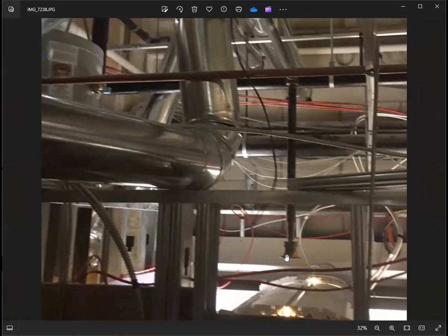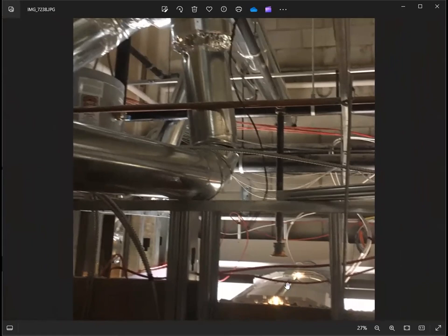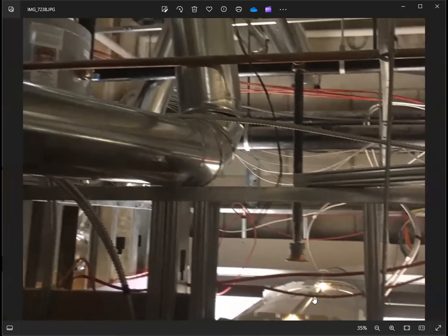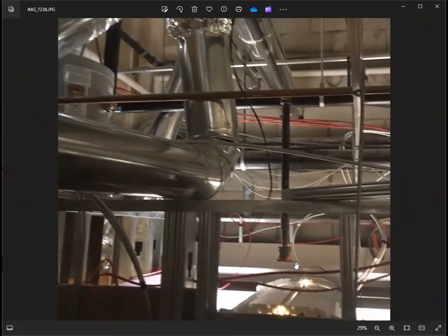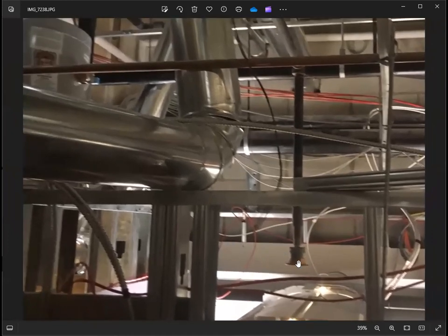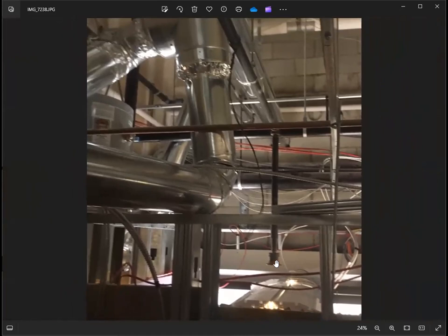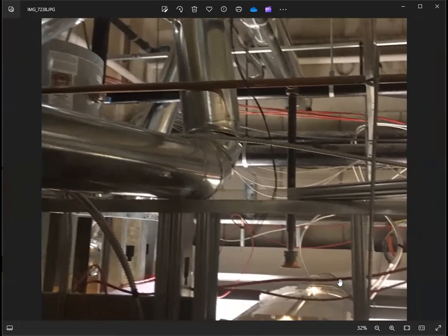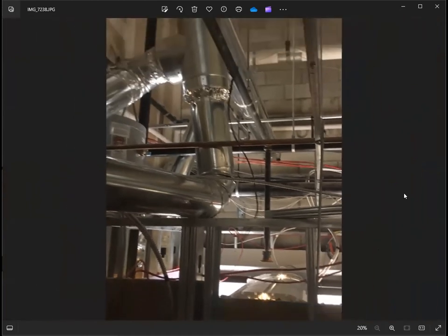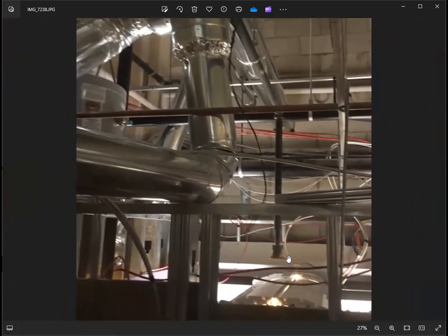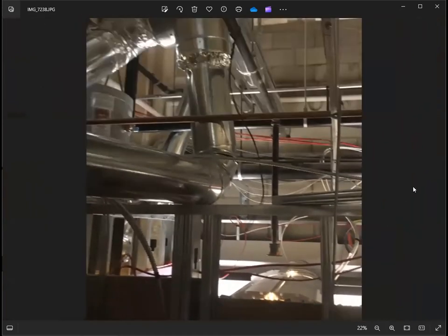So in case there's a fire condition in the area beneath the light or beneath the ceiling, this will be spraying on top and will not put out the fire in the area. So they need to have the correction here. And this will also be a penalty from the building department if they saw this. So the sprinkler needs to be corrected.